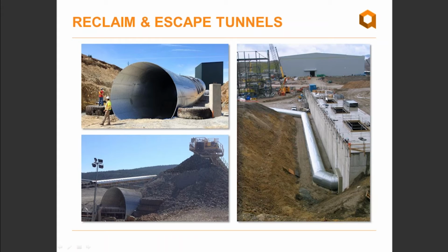One thing to note in terms of stockpiles or reclaim tunnels, usually for these applications we're cutting hopper openings into the crown of the plate. So again, we're interrupting the ring compression, which is why we have these rolled I-beams acting as reinforcement to help induce ring compression in the structure. Then escape tunnels. This was an escape tunnel supplied at the Endako mine. So again, just to highlight, we can do all sorts of custom fabrication. We can manufacture bends and elbows and all those sort of things.